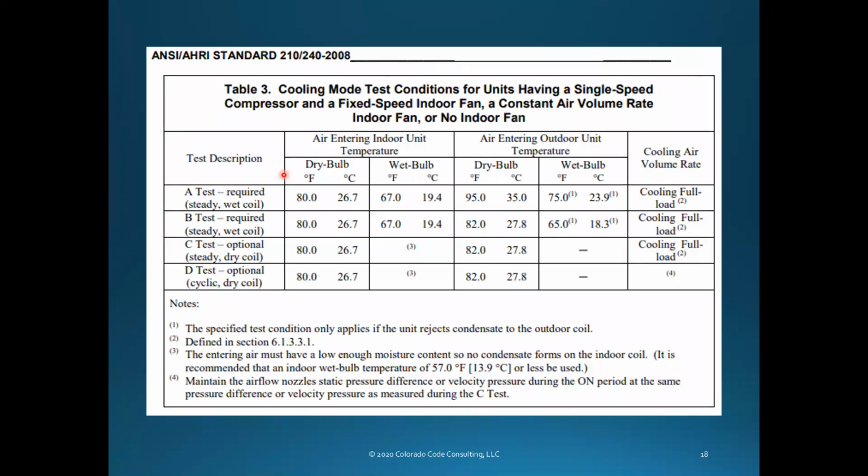So when we look at the equipment's capacity, we do not want to look at what AHRI says my capacity is. This is why we will need the expanded performance data or more detailed performance data, not just what AHRI says. Like I say, AHRI is a good, consistent standard. Everybody's got to test to the same thing. Problem is that we can't go by that because that's not what we're designing to.